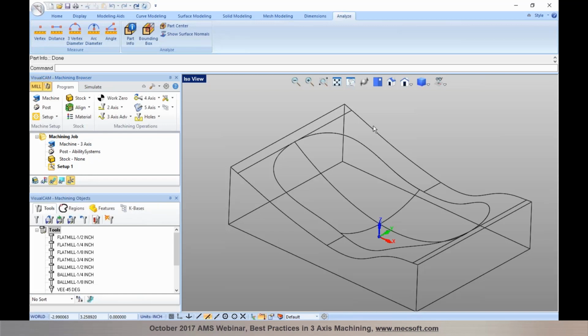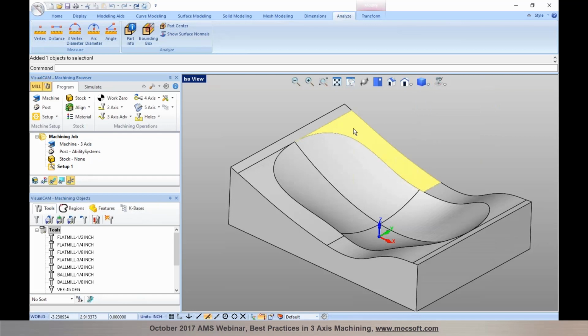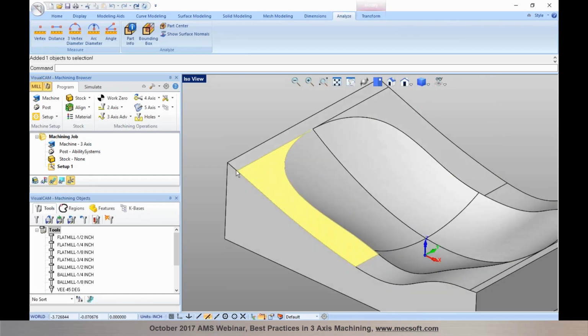So what we looked at here is an IGES model, and in the case of an IGES part, you can see that each of these are individual surfaces. They could be sharing a common edge between the adjacent surfaces. Since they are not stitched or joined together, they don't form a polysurface. Now we'll take a look at the same example as a STEP model.